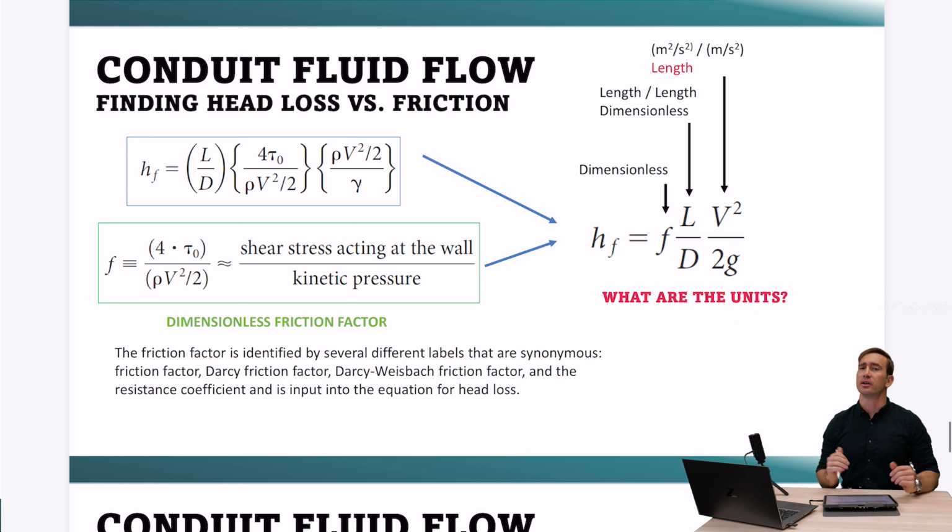So if you're doing a problem and it asks you to solve for friction factor in a laminar pipe, well, boom, you've got a super easy equation right there. So what are you going to do to calculate friction factor when the pipe is turbulent? You're actually going to need two pieces of information. You're going to need the Reynolds number, and you're also going to need what's called the roughness coefficient.